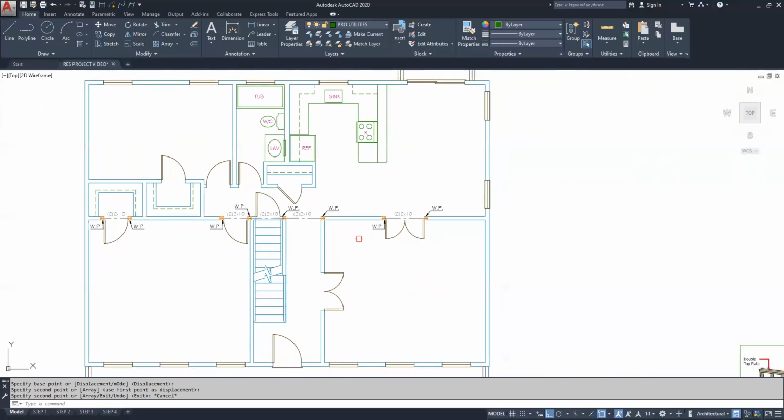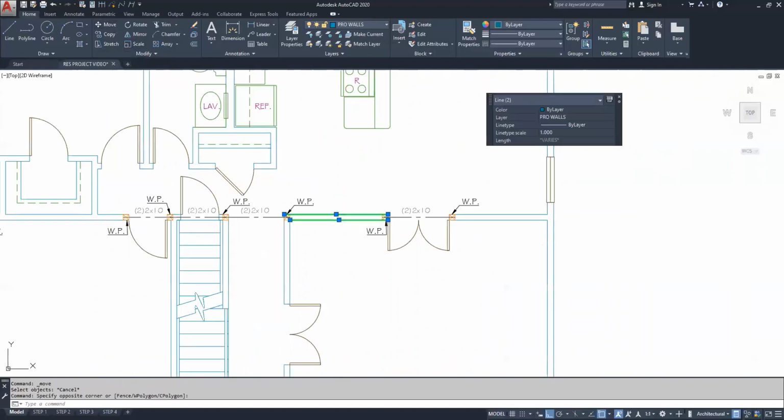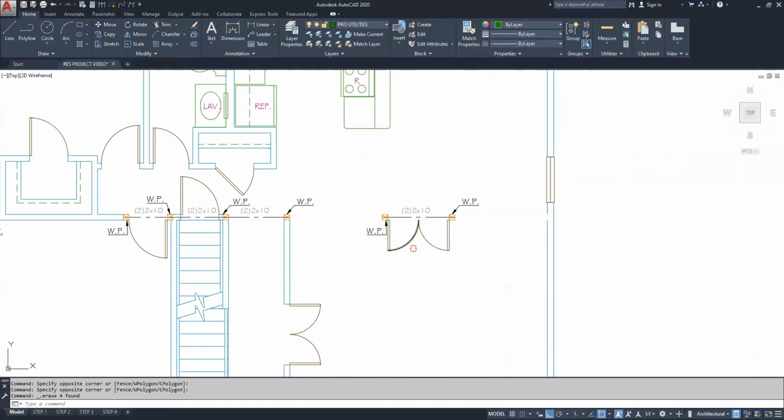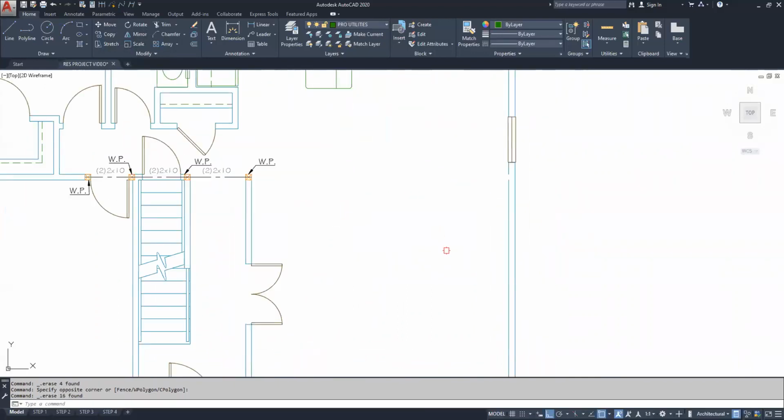What does that mean? If I decided that we wanted to remodel this house and take down this wall right here, erase this wall and get rid of this door and everything, we could, okay? What would we have to do though? We would have to put a header coming all the way across.